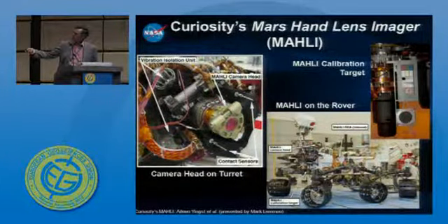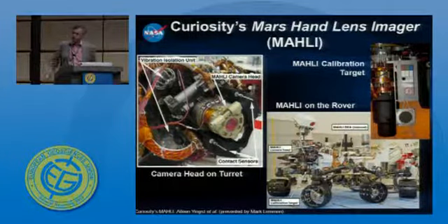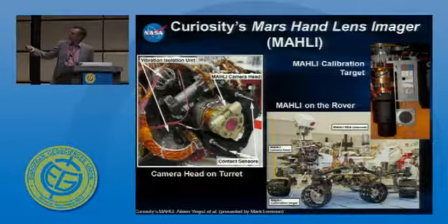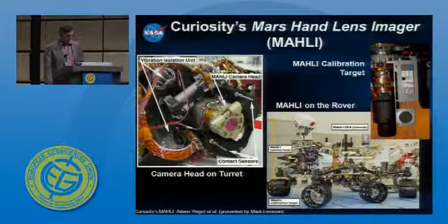And then the cabling provided by JPL goes through the arm into the rover, and I'll come to that in a moment. Also on the outside of the rover, on the shoulder joint, you've got the MAHLI calibration target, which provides color, grayscale for white balance, resolution, depth targets, as well as a US penny for scale. It's about 1.9 centimeters. Below that, you also see the APXS calibration target.